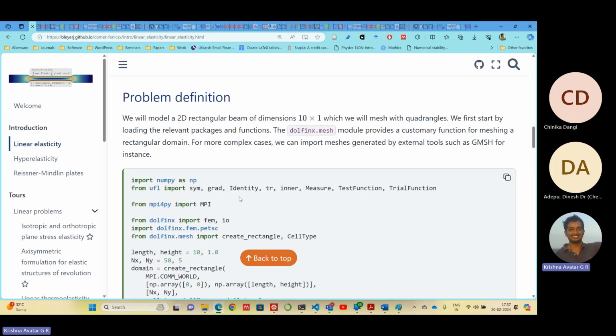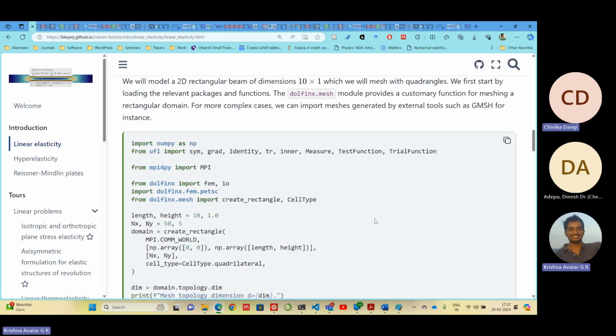We used the Python interface to the Gmsh package, defined the geometry, meshed it, and then imported it into FEniCSx. That will be interesting to do. Since the code is already written, we'll just have to run it and look at how the mesh is generated.